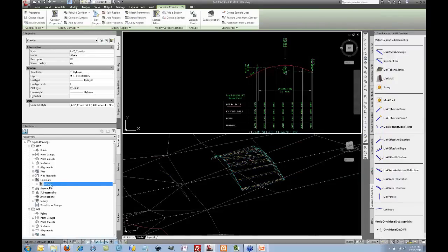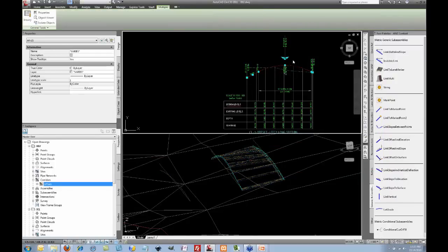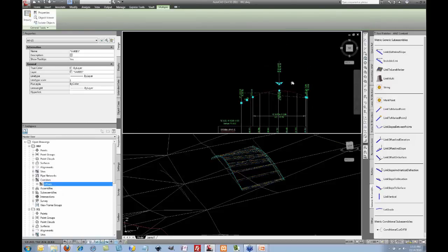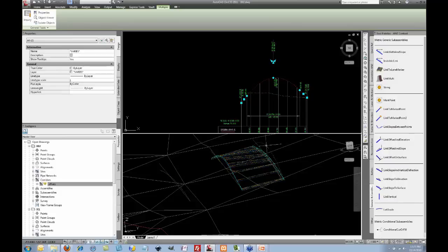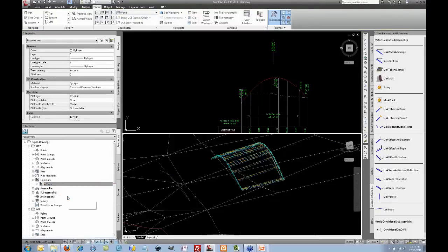So basically when I make this change, the offsets is going to give me a warning message saying you've done something. So I'll take this, I'll raise my left string way up. You should see 2 things happening here. On the bottom screen, my dotted green line shows what I've done, just where I'm hovering my mouse now. That just basically gives you an interactive view of how you're interacting with your strings. On the left-hand side, the corridor offsets is needing to be updated. So you right-click and you rebuild, and that updates for you.